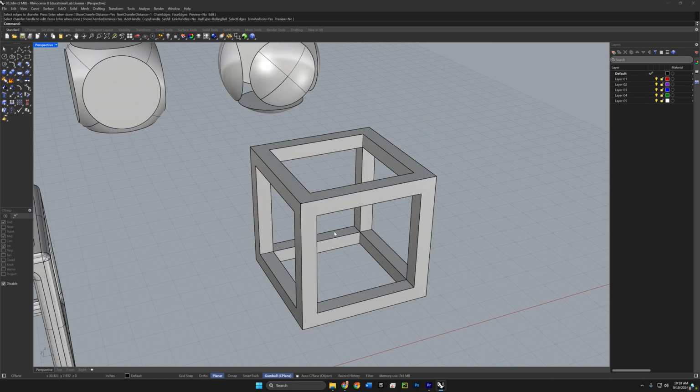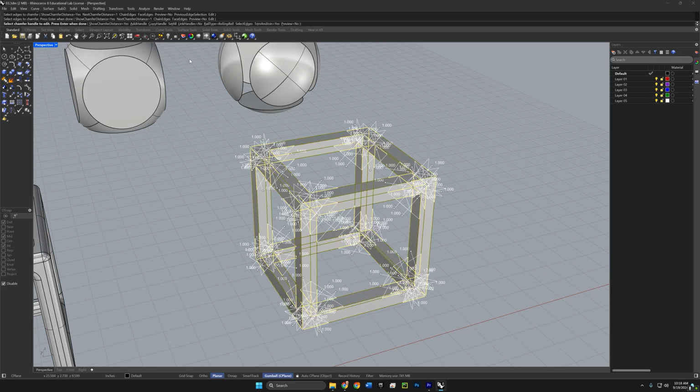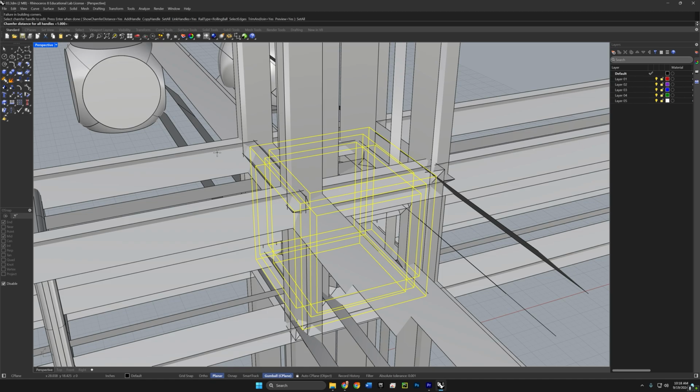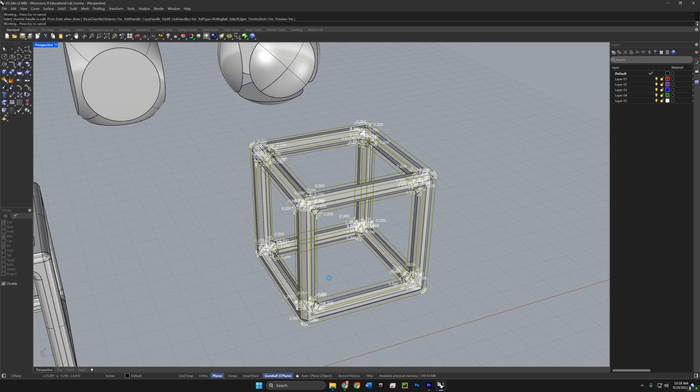Now let's run the chamfer edge command. Chamfer, C-H-A-M-F-E-R, edge. And the edges to chamfer are these. And let's see, we'll press enter to accept that. And let's link the handles, and let's turn preview to yes. And we can set all to maybe, I think 0.2 is what we did for the fillet, so that should work here too. And that looks fine. We'll push enter to accept.